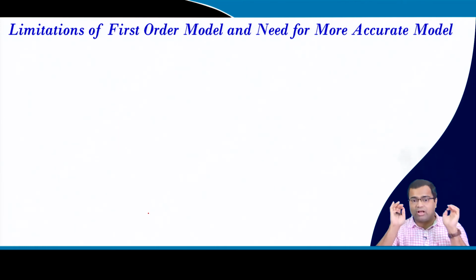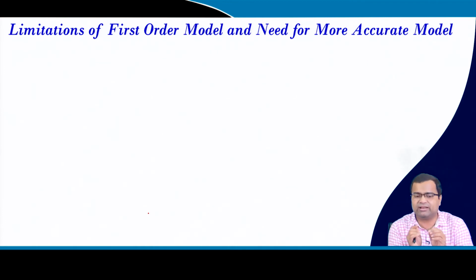That is a problem, because a ramp is needed when the duty ratio is higher than 50%, or even lower, around 0.4 to 0.45. If you use a high gain, you may get subharmonic instability. So that will be a problem when you use ramp compensation, and it can cause some mismatch in this error.